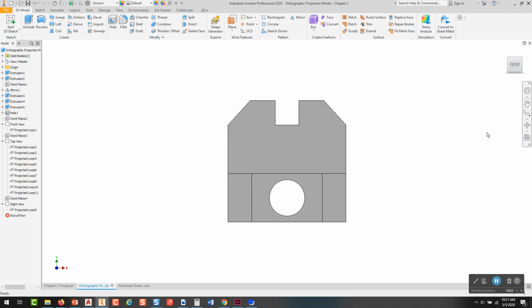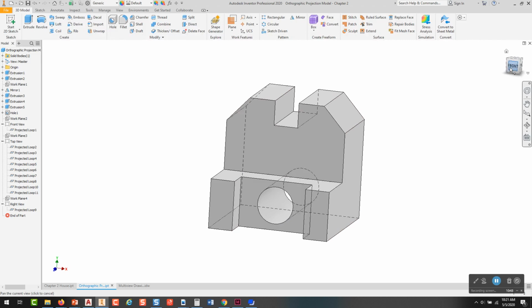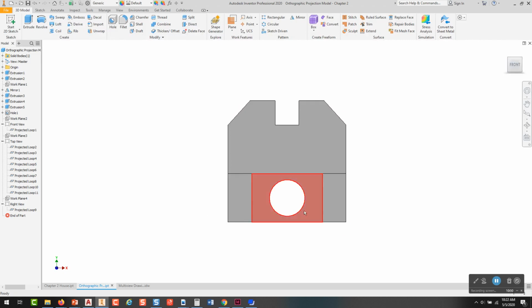I think if I could only give someone one view of the part, that probably shows the most about the part. So I'm going to go back to here. So imagine that you're thinking, or that you have this part. You could choose any view you want to be the front view. I'm going to select this view here, and partly that's because I see this hole that goes through the part, and I also see this groove that's cut through the part. I see these angles that we call chamfered edges over here. I can see a plane here, a plane here.